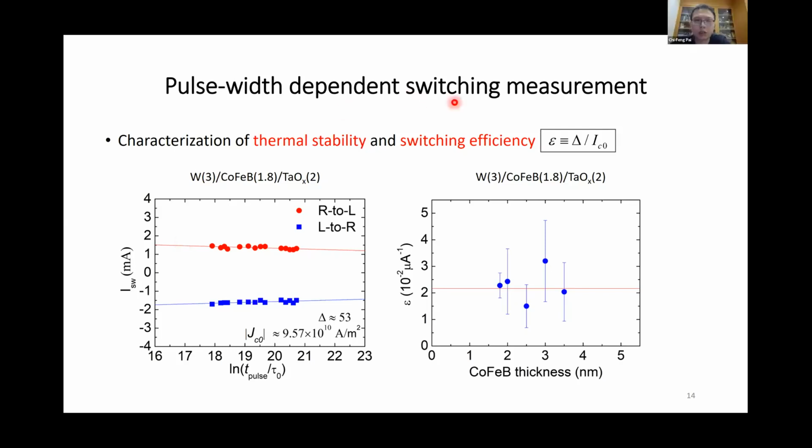Yeah, that's true. So the estimation should be pretty rough because, like I said earlier, the thermal stability might correspond to a certain volume of the ferromagnetic layer on this patterned film. But the switching current IC0 that we extracted is actually flowing through the whole device.